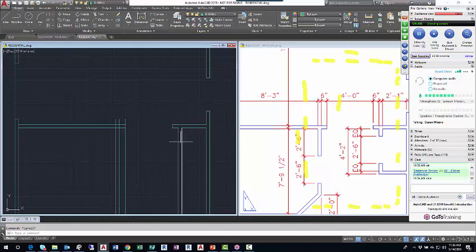And the clean wall intersections indicate that these are the same material. The material flows through these. This is a 2x4 stud up against a 2x4 stud, up against a 2x4 stud. And that's what we're seeing there. That's why those lines are all trimmed out.